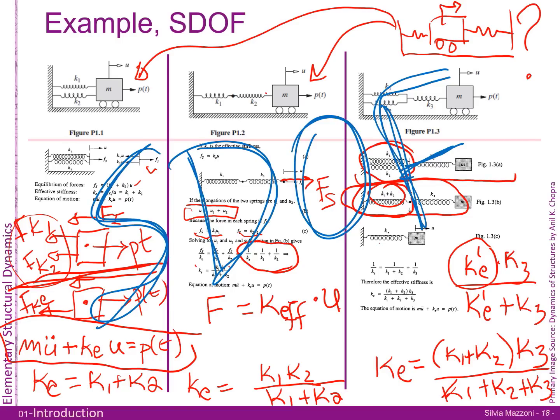What does that tell me as a structural engineer? What do those springs represent? They represent beams and columns. And I've got to figure out how to combine the resistance and the stiffness components of the beams and columns. Maybe I've got beams and columns coming in from the left, from the top, and different directions, okay? This is supposed to be simpler than beams and columns, but it gets a little bit harder to visualize. But that's the example that I'm going to give you next, or after the next one, on how we deal with frame elements, which get a little bit more confusing because these are simple Ks. Now we're going to be dealing with EIs over L cubed and EIs over L squared and terms like that, okay?